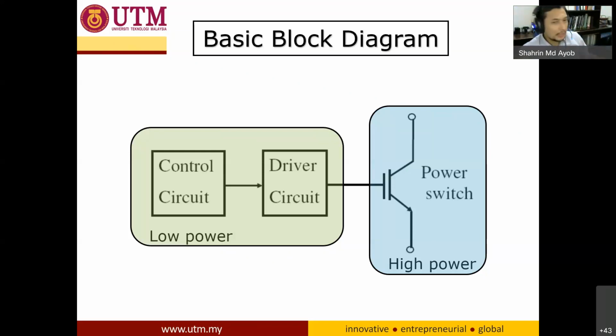So this is where you need a gate driver. The gate driver will increase the voltage from 5 to 15 volt. That is the purpose of the gate driver. So the gate driver is the interface between the microcontroller, your Arduino Uno, and the power circuit.